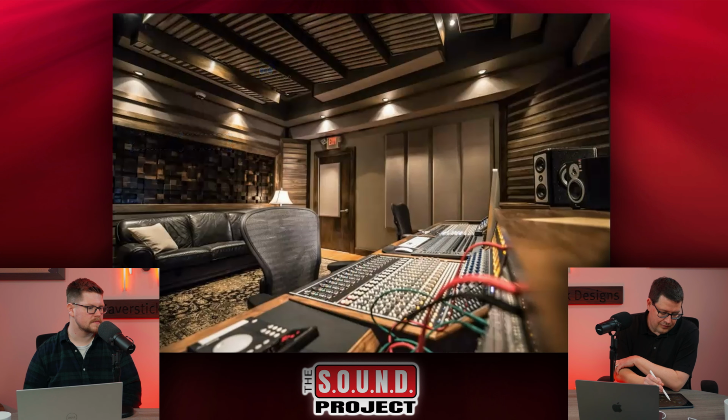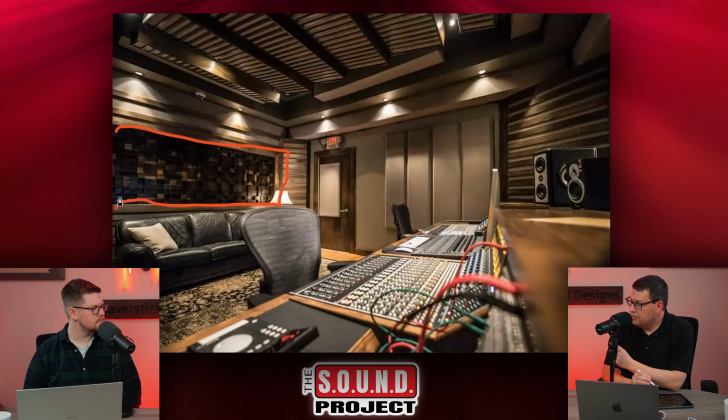On the back wall, you can see this diffuser here. It's built into a bass trap like we typically do, but it's just made out of different 4x4 posts that are the right depth. So it's very heavy. That's the other thing about building your own. When you go to a manufacturer, they've optimized it for weight and structural stability, whereas sometimes people will build it like this, where it's just really, really heavy to install, and you got to make sure the wall is braced properly.